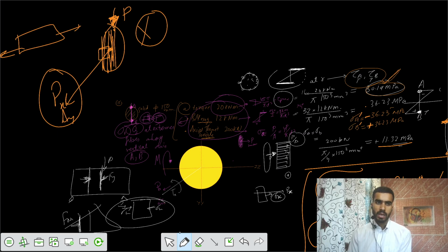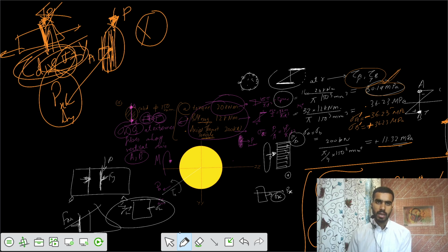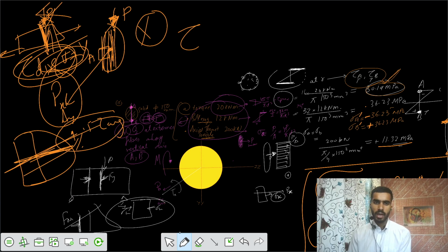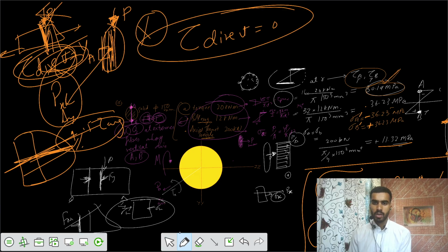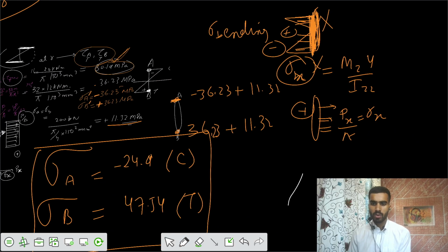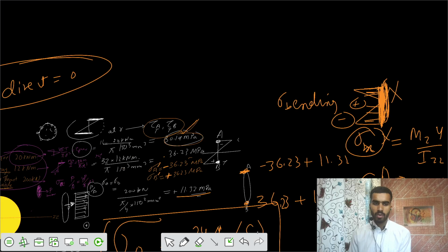That's in this way. But there is no load that's transverse. There is no load vertical, that's tangential to the surface. That should give you direct shear stresses of V by A, or you can say we have equation 4 by 3 tau average, that we have maximum value of 1.5 tau average. That's we can say tau because of direct shear stresses, that is 0. That is 0.